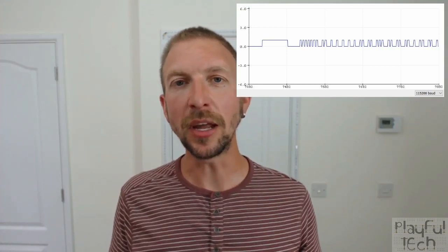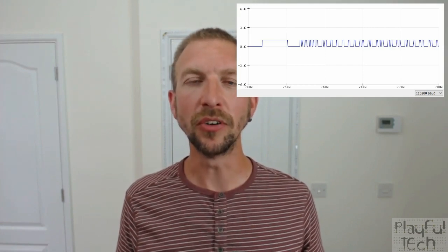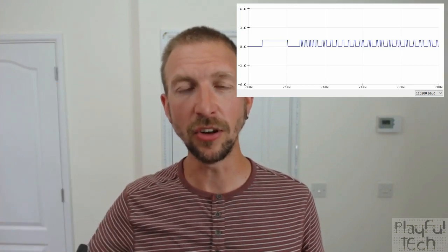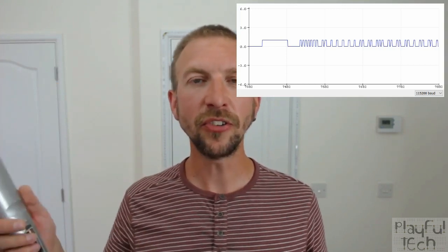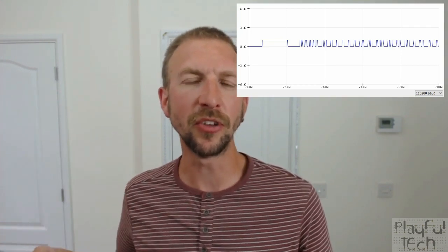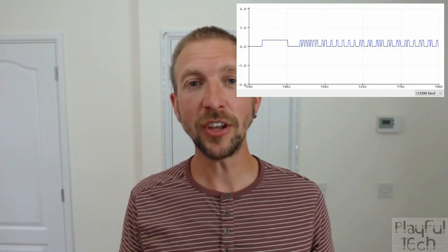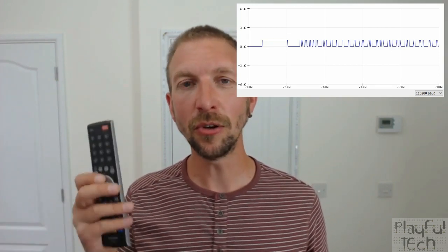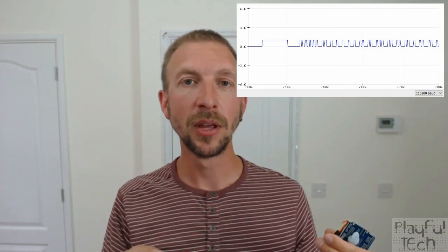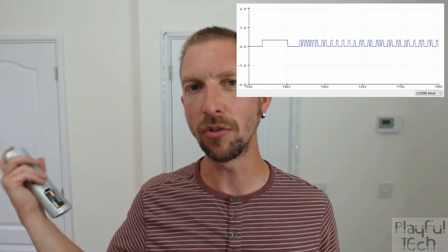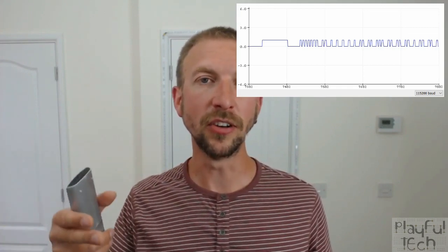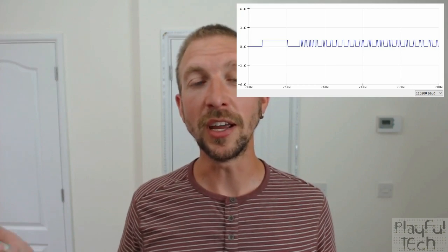So you can think of this a bit like a kind of infrared Morse code if you want. There's a sequence of dots and dashes, or flashes and periods of time when the LED is not flashing. And devices all around you that have remote controls are communicating via this kind of infrared Morse code type signal. But you're not able to see it at all, but it's happening all around you. So long as there is a line of sight between the LED here and the receiver, because remember it is a type of light, so it's not going to go through walls or anything, but you can encode messages using this pattern of flashes.